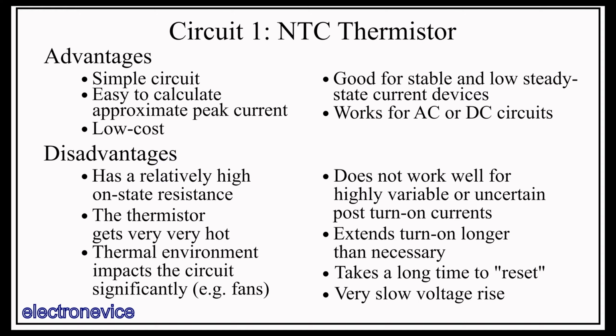On the disadvantages side, it has a high on-state resistance relative to something like a beefy power MOSFET or a relay. Recalling the table I showed, the minimum resistance I measured was only about 92 milliohms, and that was for the 10 amp version at its maximum current. The lower current thermistors had even higher resistances, and the half-max rated resistances were even higher. This leads to significant amounts of power dissipation that could make your system much less efficient than you might like.